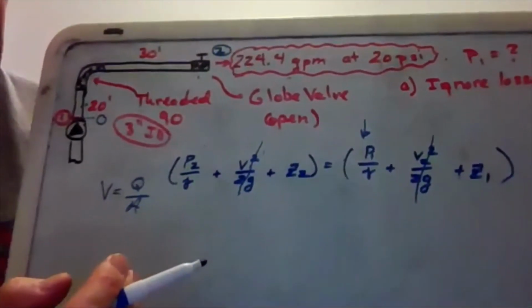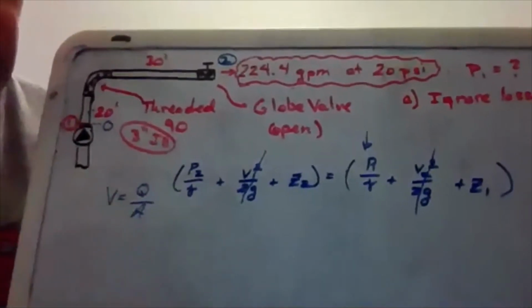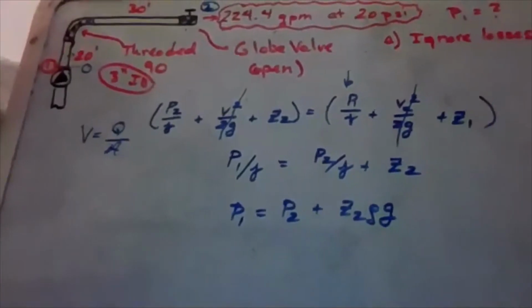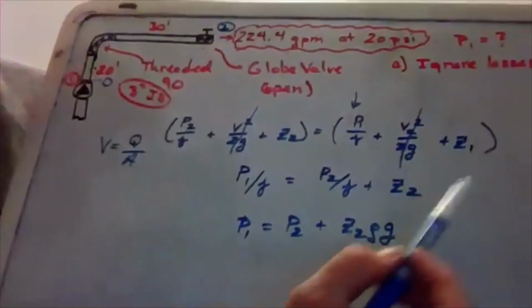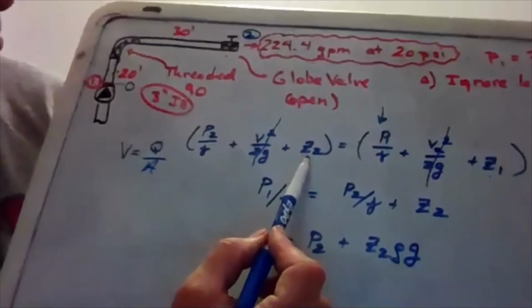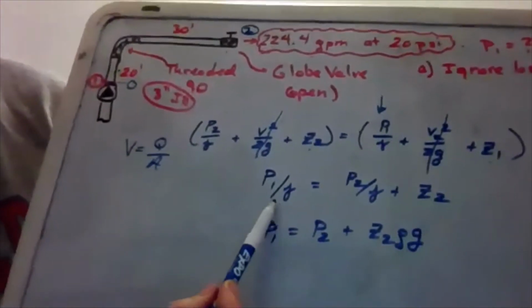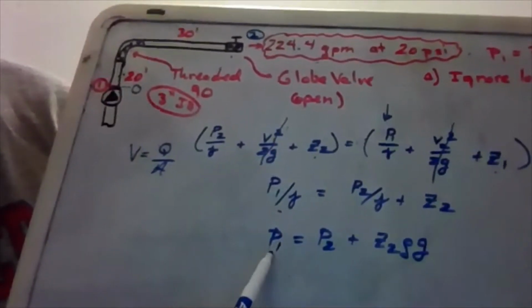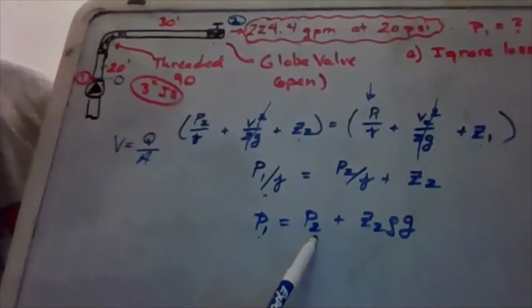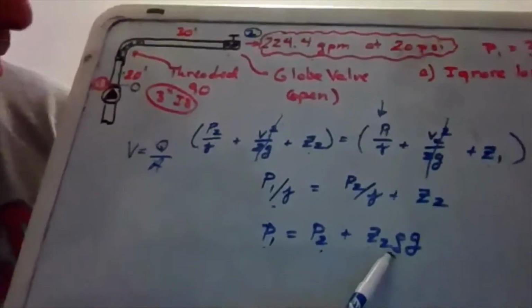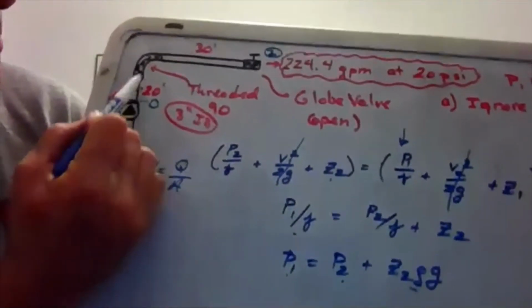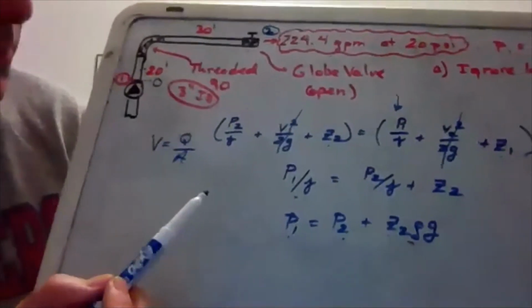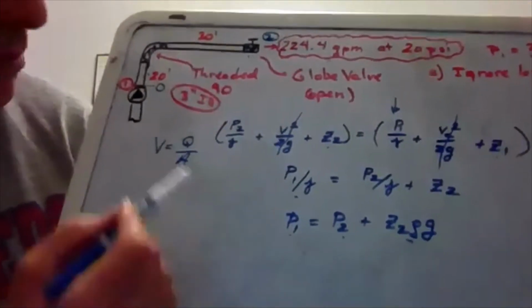Hey, well, let's simplify that equation, maybe solving it first and see how it turns out. Okay, so I'm not as algebra oriented as the book. They do a ton of algebra, but here this is not bad. Z1 is 0, Z2 we're going to fill in later on is 20. I just went ahead and did the algebra, okay? And if I think about simplifying it, it's saying that P1 has to be bigger than P2 by this quantity right here. We've got to have enough pressure so that we get up there and have that 20 PSI. We're going to lose pressure as we go up. Okay, let's just go ahead and crank through the numbers and see what kind of pressure that turns out.